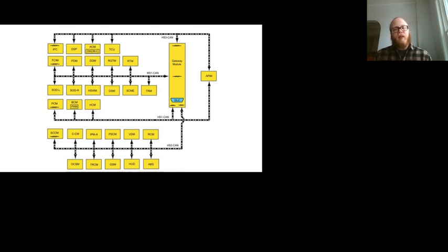Because of that, we're limited to the size and shape of the data link connector, because that same scan tool has to plug into everything. So we only have 16 slots for wires to go into. And when we have 4 communication networks, that takes up half of the slots all by itself. And some of those slots are meant for other things than just communication networks.